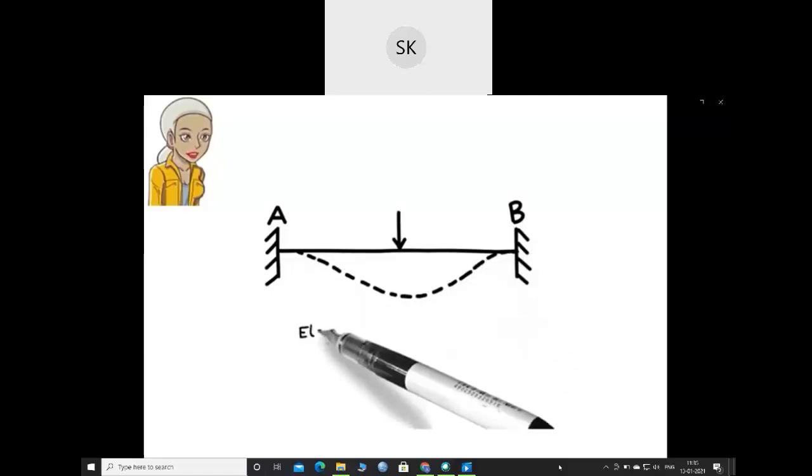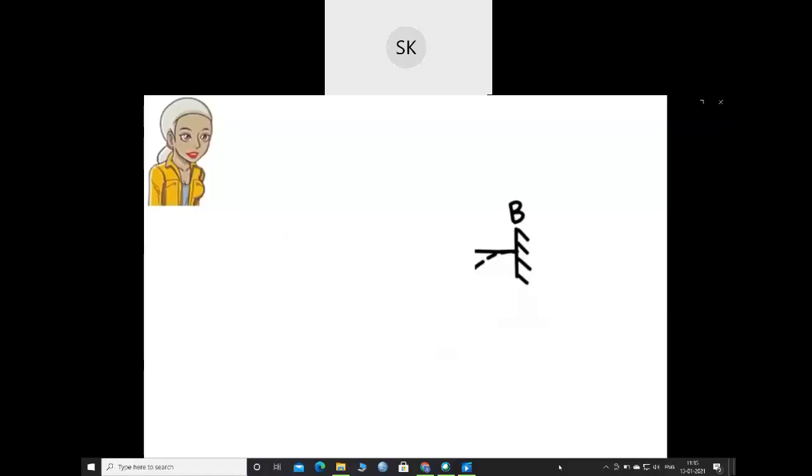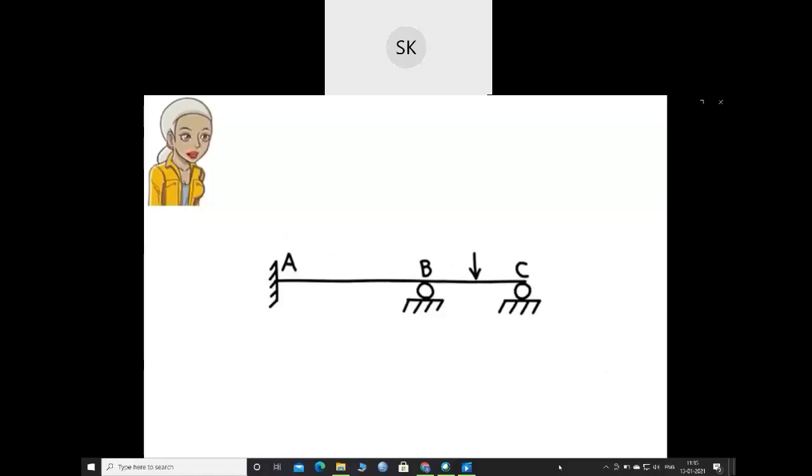That is, the geometric center of the trapezoid is 7 meters away from the left end of the beam. The elastic curve, also called the deflection curve, for this beam has a zero slope at A, a negative slope at B, and a positive one at C. So the elastic curve looks like this. Here is the free body diagram of the beam when the distributed load is replaced with its equivalent concentrated load. We can now write the equilibrium equations and solve them for the unknown reactions.